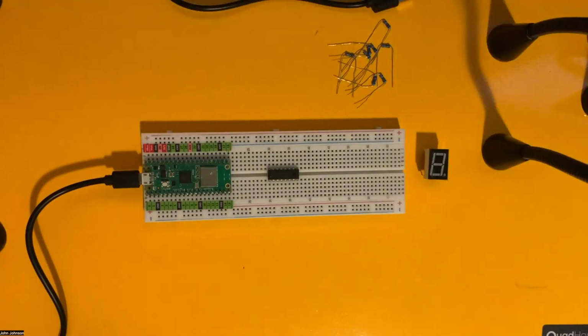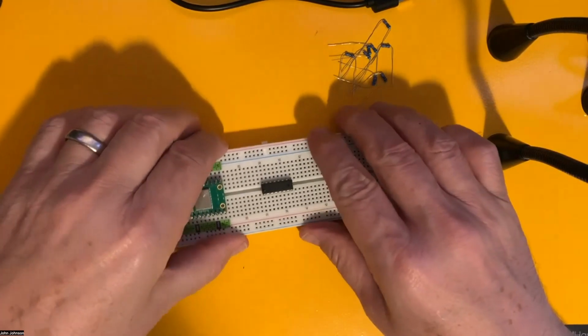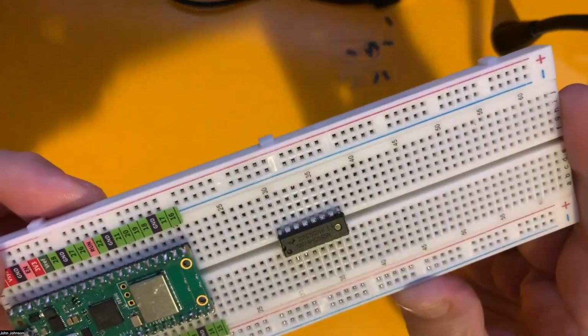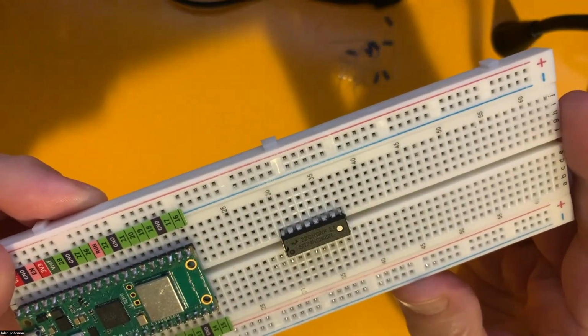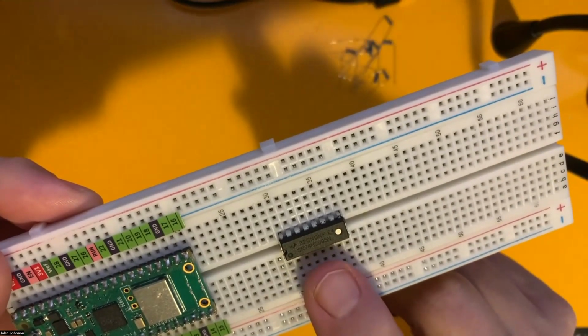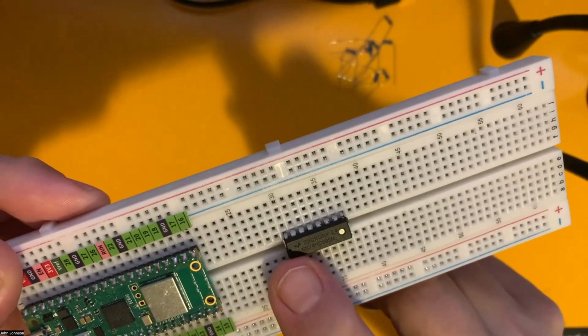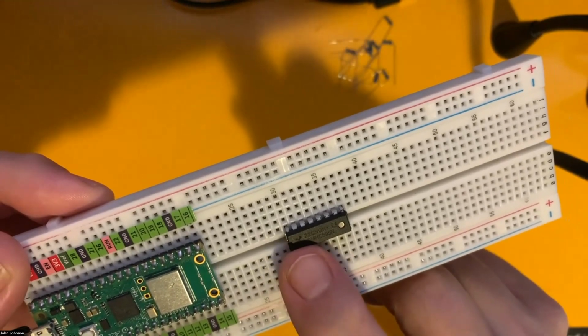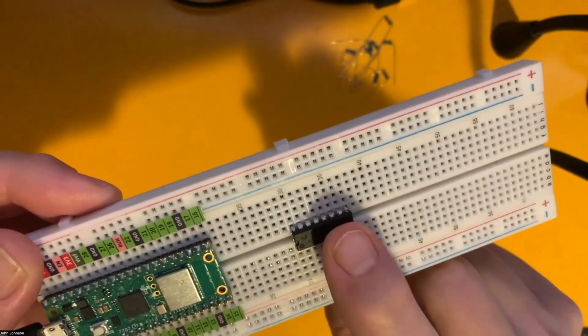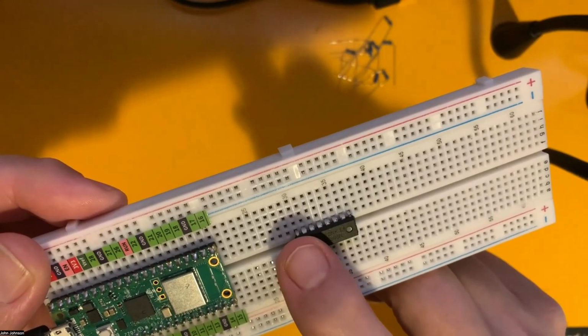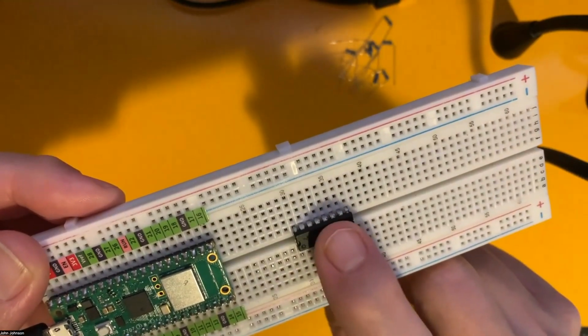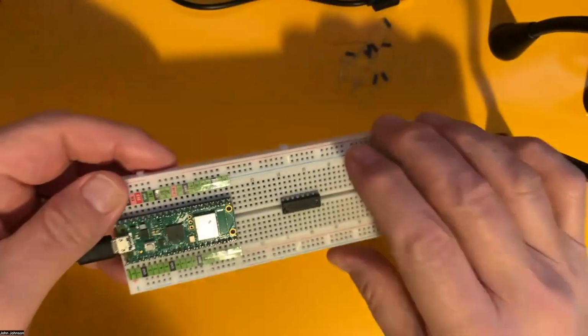So here we've got our setup. Let's go ahead and pry the chip off there, because if we zoom in, notice that it says 4HC. So we can tell our orientation, and notice the notch in the chip right there. We're going to have to reverse this, and be very careful, because you can bend these. The legs on this are very, very delicate.